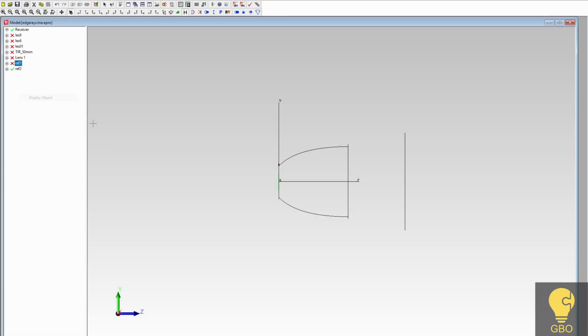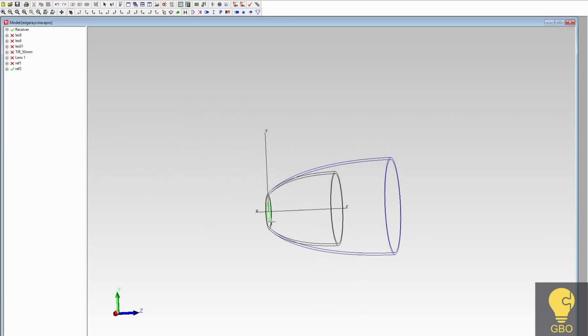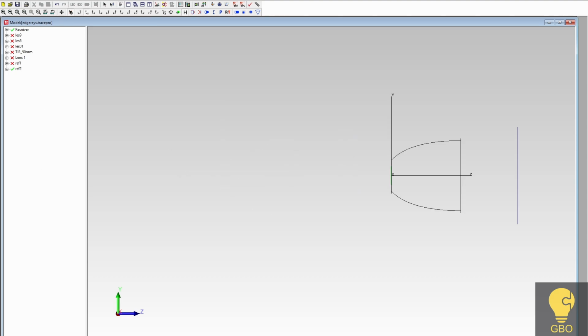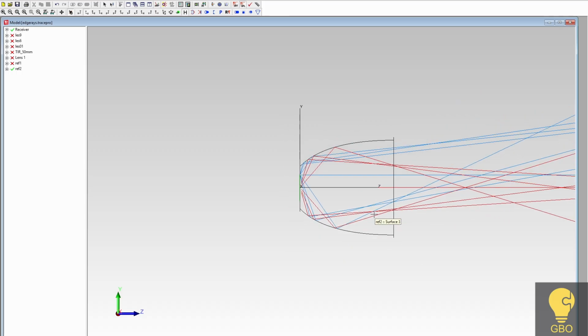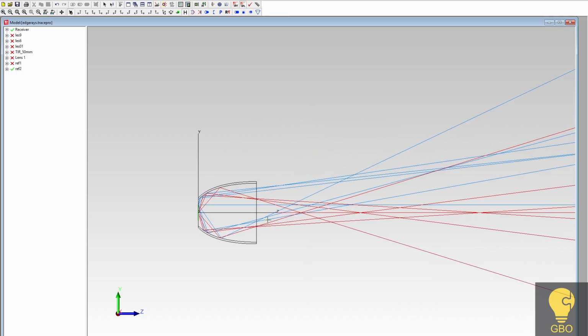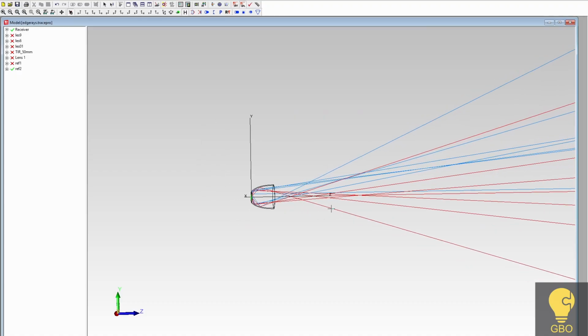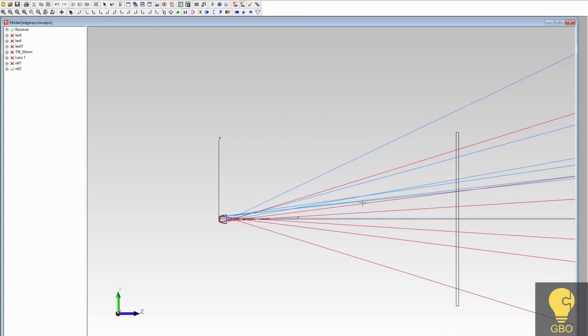So let's run the simulation for two different reflectors. One designed with only the point source in mind, and the other where I tried a little compensation for the extended source. Here we have two ray fans, one centered in the origin and the other offset by 4 mm from the center, which represents the border of a medium-sized LED.